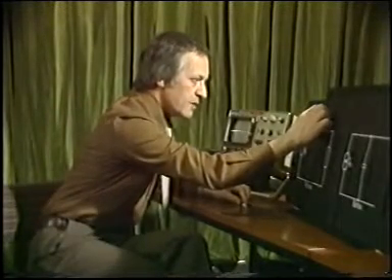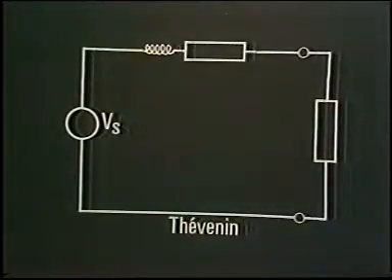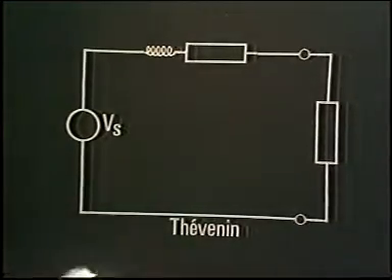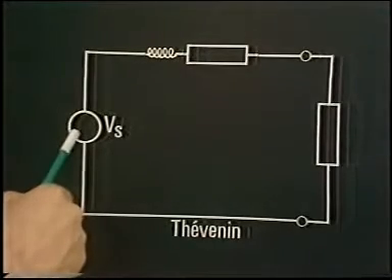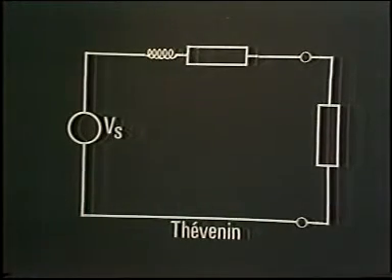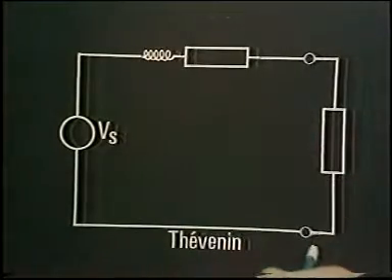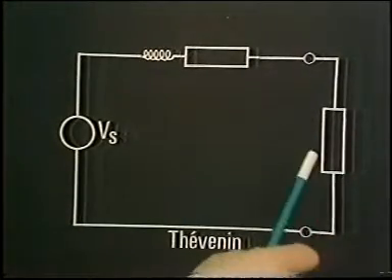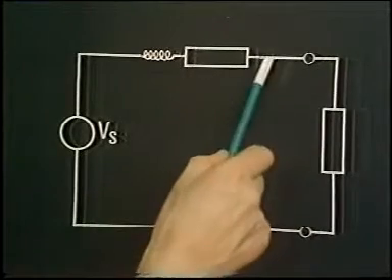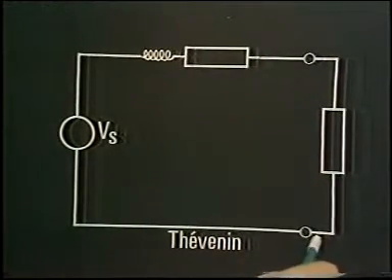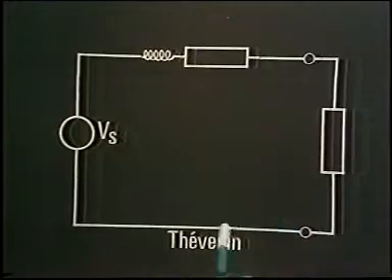There's our output impedance. Now, if we weren't to do the technique I was just talking about, turning off the internal generator, how in general can we find that output impedance from a circuit where it's not possible to turn off the generator? Well, the same technique can be used as you used before with the sine wave oscillator and the generator scope, that is, apply a load and measure the output voltage. But in this case, where the internal impedance is complex, it's necessary not only to measure the output voltage, but its relative phase, and use the techniques of AC circuit analysis. And this is where phasors come in.